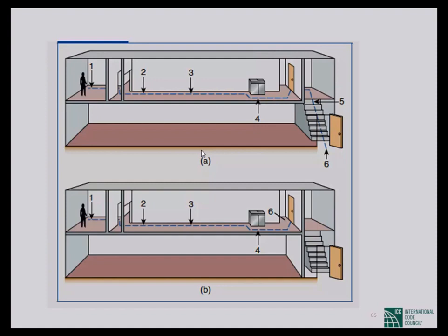So how is each travel path measured? It is from the middle line, and if it is not a fire door, then up to here it is travel distance. If it is a fire door, up to this is the travel distance. This is the fire door. This is not the fire door. This is the variation. If it is a fire door, up to this is the fire travel path. So from any point, the same distance is the travel path.